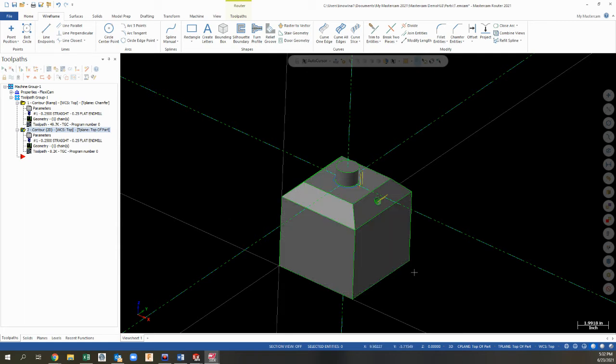So we have a couple tool paths. So what we have now are levels. All right. This is something that's very helpful when we get into multiple operations. We have a lot of features. We want to be able to get some clarity with what we're looking at. Levels are essentially like a folder. Just like a folder on your desktop, you'll be able to assign features such as solids, surfaces, wireframe, different geometry.